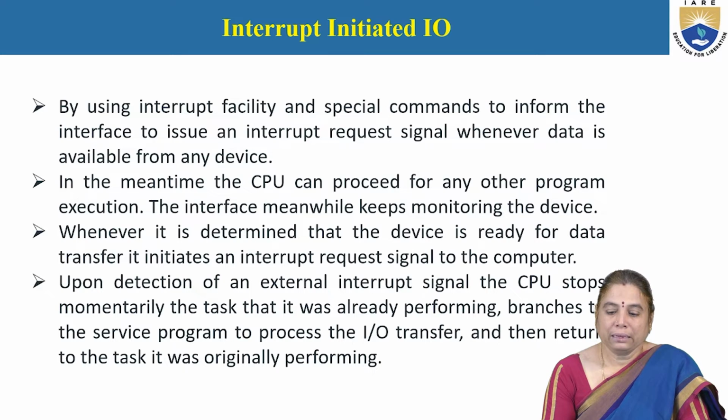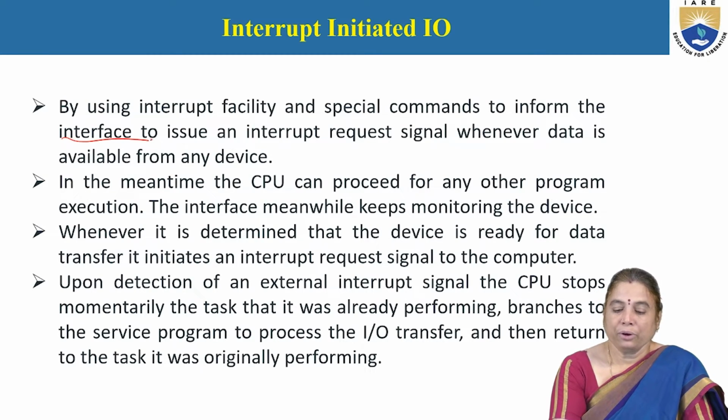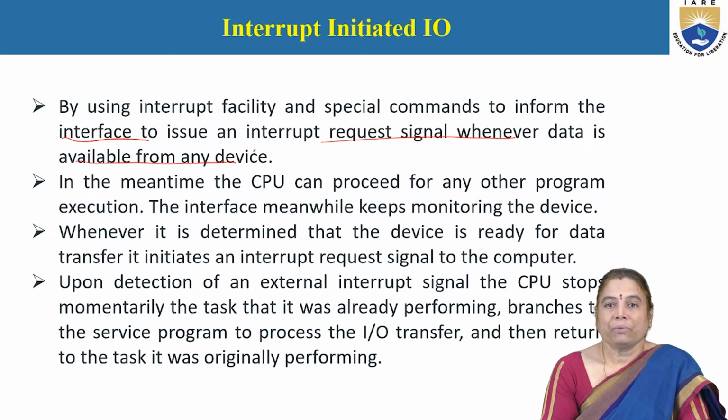The second method is interrupt initiated I/O. By using the interrupt facility, special commands inform the interface to issue an interrupt request signal whenever data is available from any device. So whenever data is available, the interface raises an interrupt signal so that the CPU can temporarily suspend the current program execution and service the device for the input-output operation.